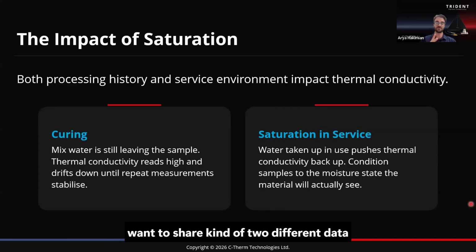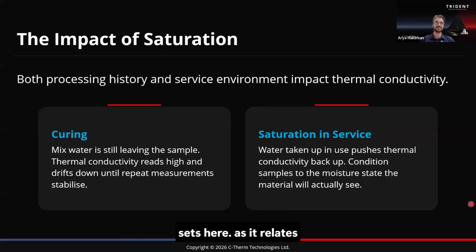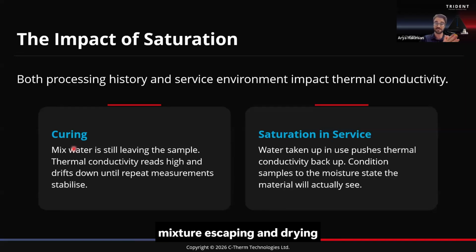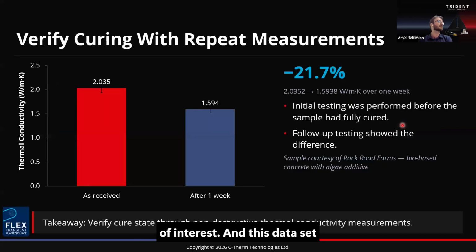But I want to share two different data sets here, as it relates to materials being potentially saturated from the curing standpoint, so in the process of forming the samples, that water within that mixture escaping and drying out to form that final product, as well as purposefully introducing saturation into your sample to mimic the in situ or in-application conditions of interest.